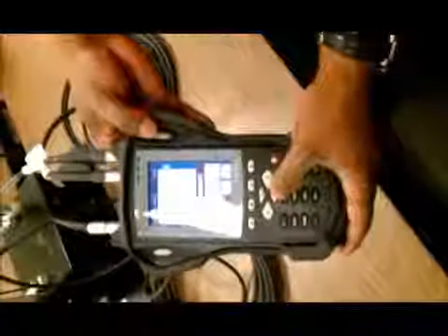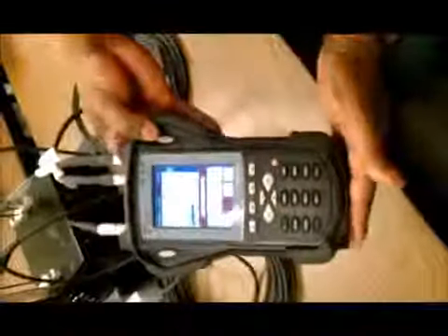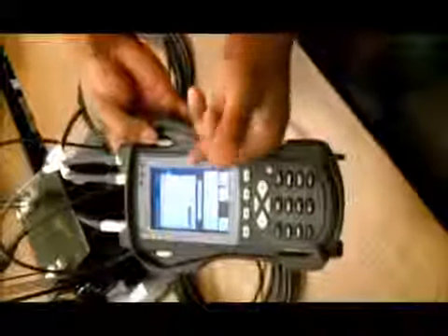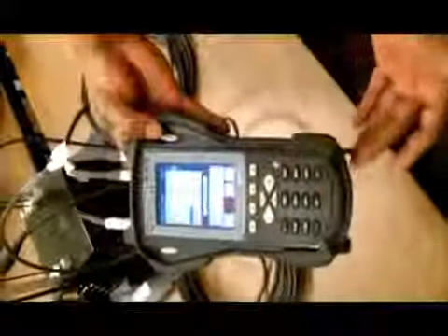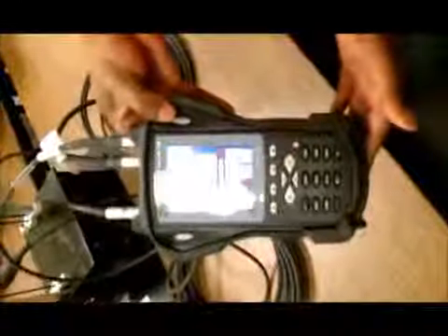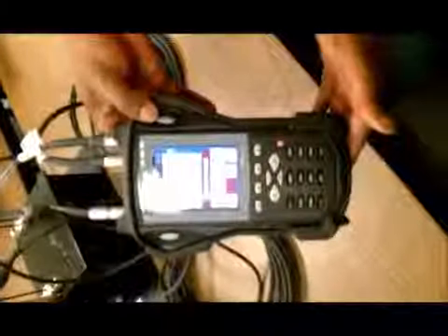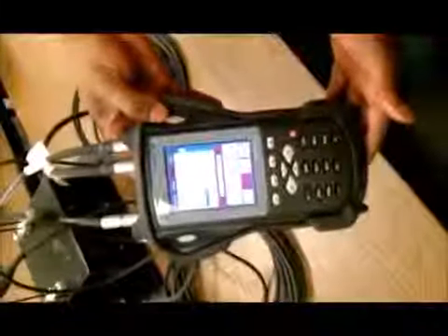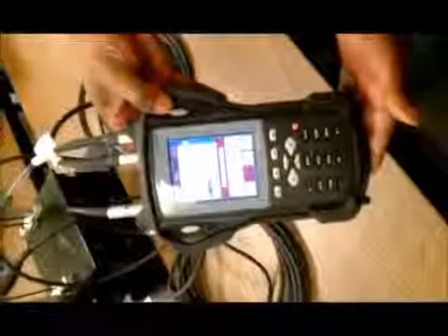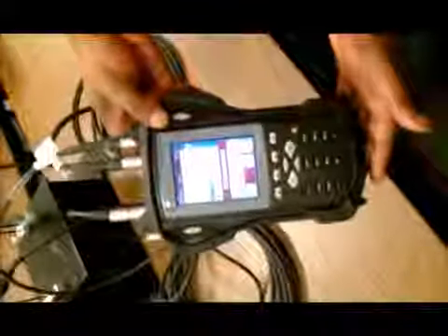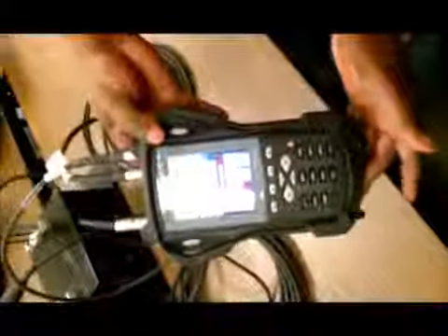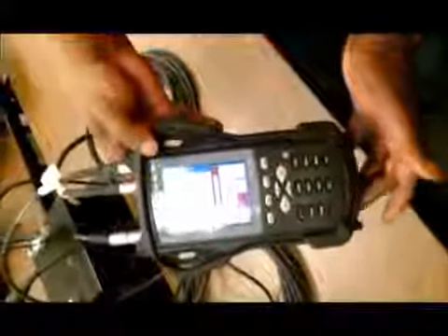And the next part that will be of interest is how we're going to view the signal, whether it's just spectrum, the graph itself, or if it's spectrum and phase angle. For the spectrum, you just use one channel. For the spectrum and phase angle, you'll have to use 2 sensors. Your second channel sensor will be used as a reference point.